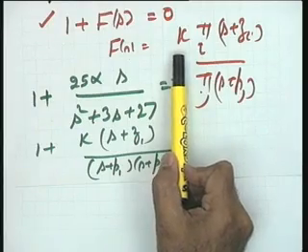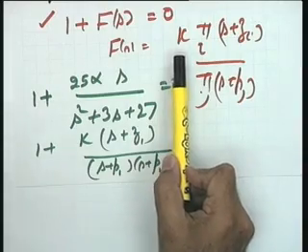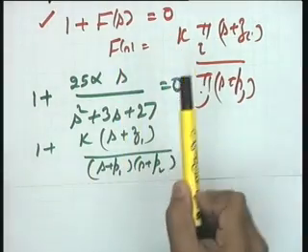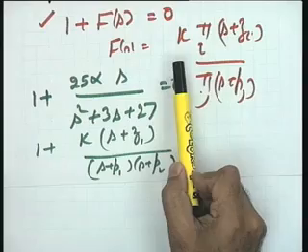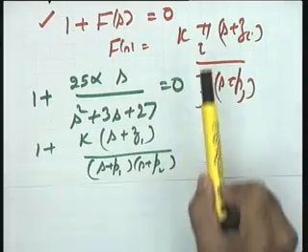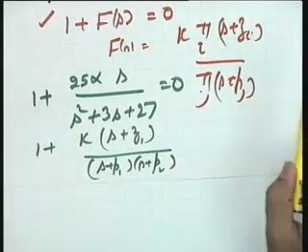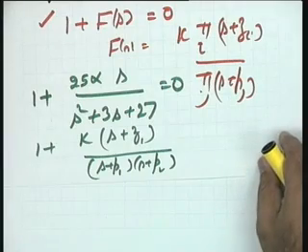The only thing is this, that your characteristic equation should be reformulated in such a way that the parameter of interest comes as a multiplier. This point is to be noted, and that parameter of interest which comes as a multiplier will be referred to as the root locus gain. Okay. Examples will follow, the design examples will follow, don't worry.